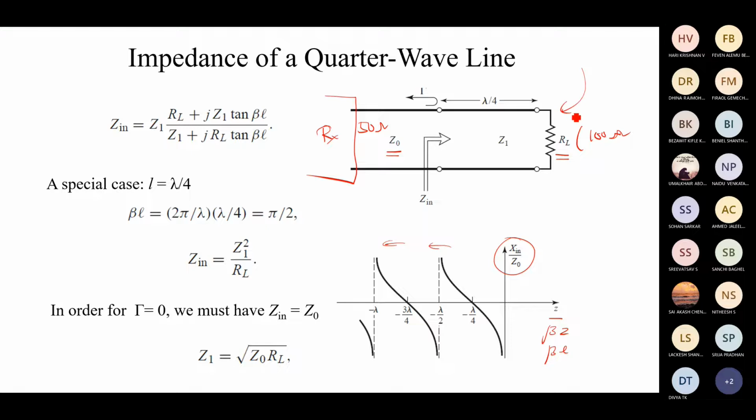So from here the signals are received and they are supposed to go to here. So this is the basic problem. Now we have to make an impedance transformation by using a quarter wave transformer. So this quarter wave transformer of length lambda by 4 with the characteristic impedance of Z1 can simply transform this impedance to this without any issue. So the impedance will be matched.